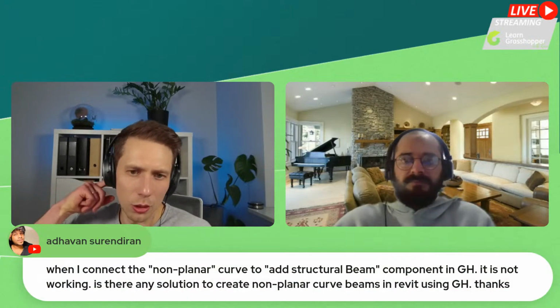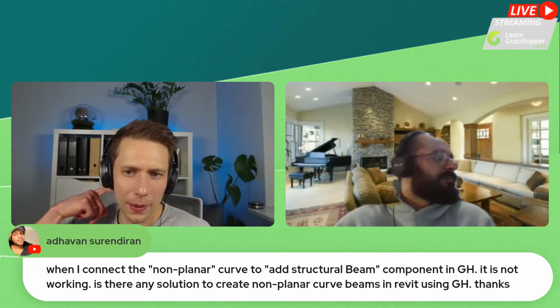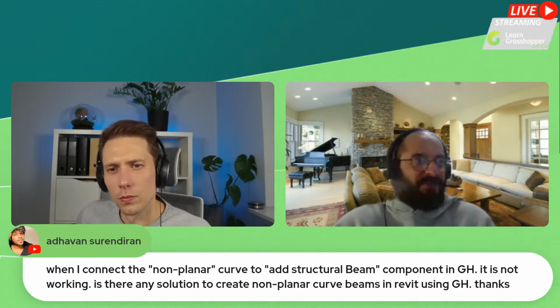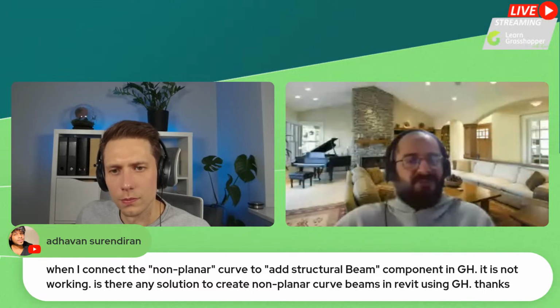When I connect the non-planar curve to add structure beam component in Grasshopper, it's not working. Is there any solution to create non-planar curve beams in Revit using Grasshopper? I think you need to explore that curve. Maybe that's a continuous curve or maybe something like that. Because when you add detail lines in Revit, if your lines are continuous, you will have this problem. You need to create discontinuous line.